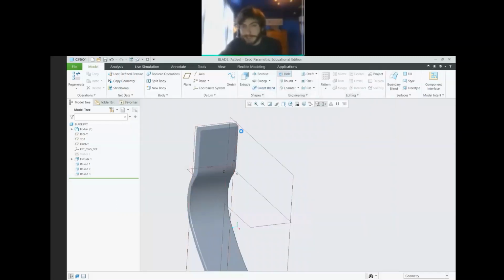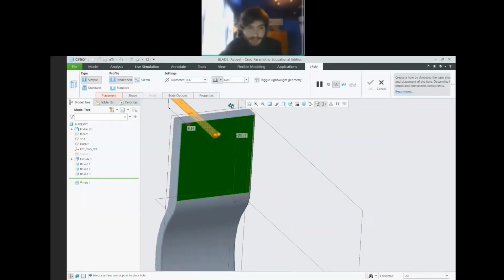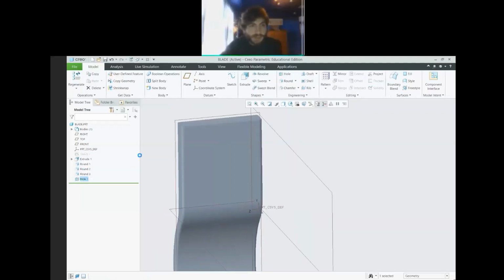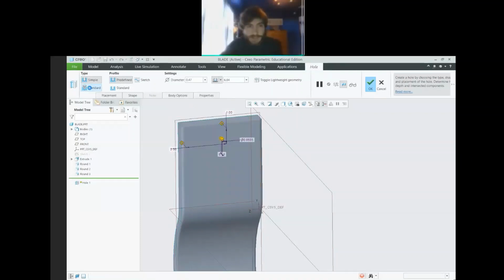So put a hole, we'll click this face, and you see we get these 2 little red handles. So we'll drag one to this top face, one to this face on the left. And you see, once we did that, we got extra dimensions. We have this 1 up here. We have this other one up here. So we made it 5 inches across, so we'll make that halfway. Okay, so then what we're going to do is create a standard hole.